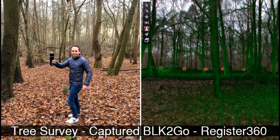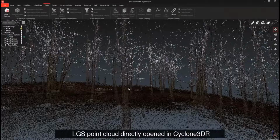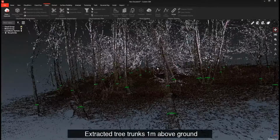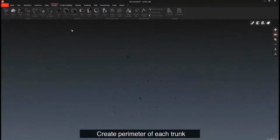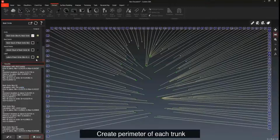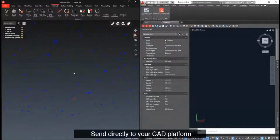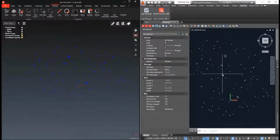Exactly. So what we want to do here is test, challenging the BLK2GO in a different environment. Tree survey. At the end of it, we want to get a tree survey out of it. How to do it? We need to get every single trunk of each individual tree, and here we separate our point cloud, use a digital terrain model, use the best fit circle to each trunk, and send it to AutoCAD.